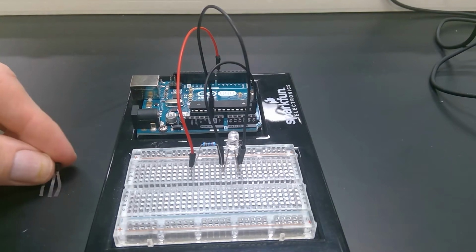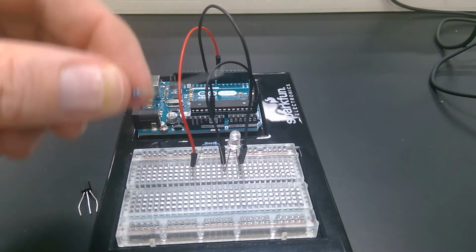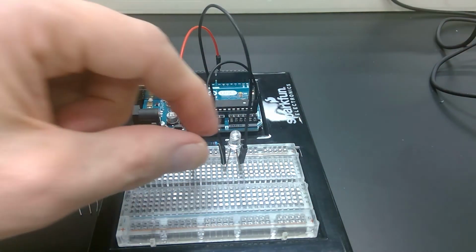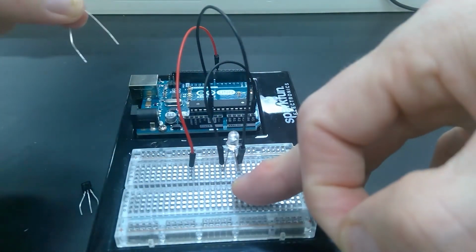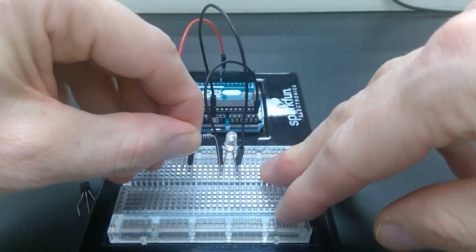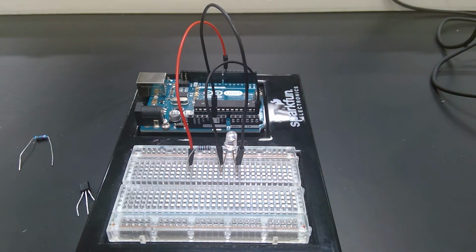All right, so here is the temperature sensor, and the temperature sensor is utilized with a 1,000 ohm resistor. So the first thing I'll do is pop out the 200 ohm resistor and put the 1,000 ohm resistor in there. Now I will say that when you come to the lab, you're not going to do this. You're actually going to build a separate circuit somewhere else on the breadboard because you need both of these circuits at the same time. But I don't. I'm just trying to demonstrate here.